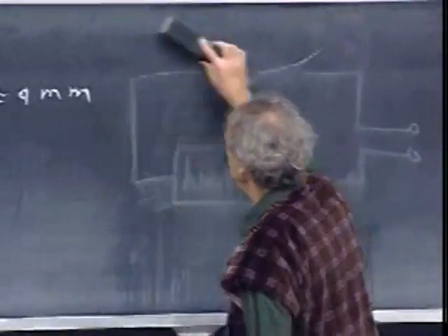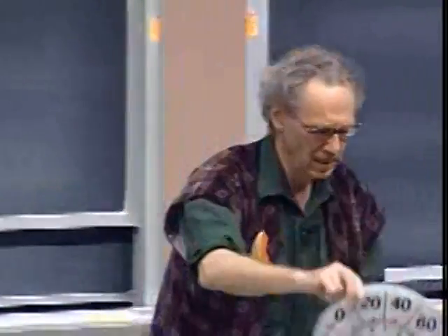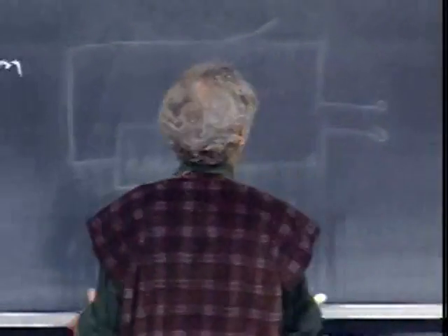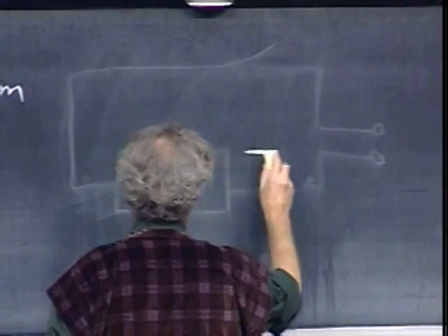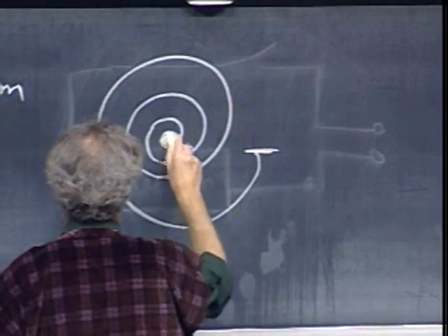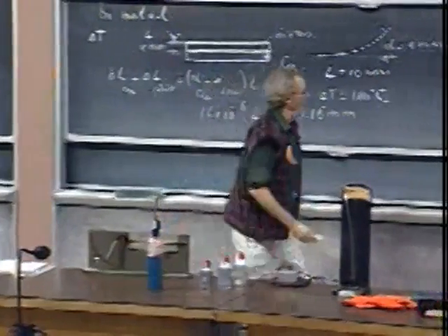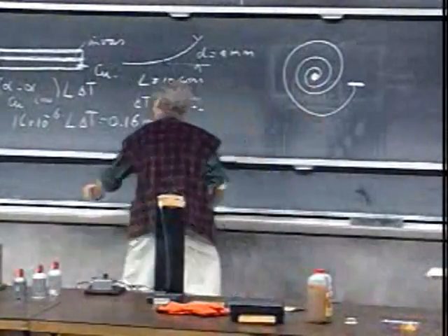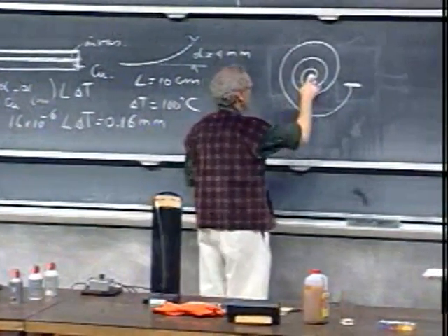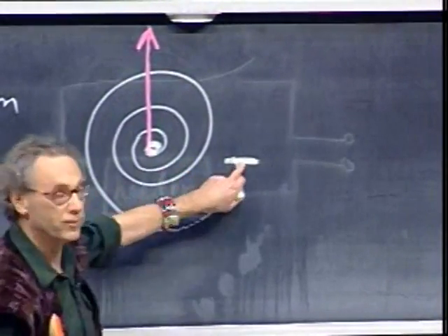In fact, the one that you see right here is driven exclusively by a bimetal. If you look in the back of this thermometer, and I will show that to you shortly because I broke one open for you, then it looks like this. There's a coil. This end of the coil is attached to the plastic casing. And here is the red hand. It's a pivot here. The red hand.